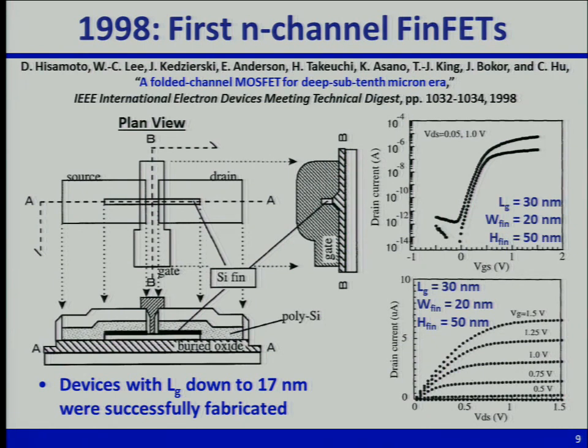So yes, that DIBL is less than 100 millivolts per volt of drain voltage applied. So we demonstrated we can actually suppress short channel effects pretty well, and the output characteristics look pretty well behaved. Notice the spacing here is pretty equal as we increase the gate voltage by equal increments. So clearly this is a short channel effect. The current is limited by velocity saturation.